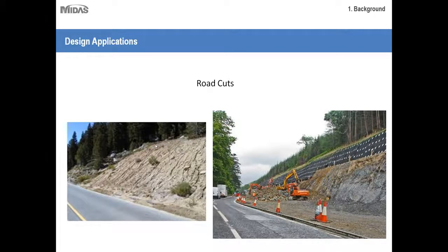As you can see, because the slope appears to be made of harder or stiffer materials, there aren't any tiebacks, and it's very close to the road. So in other words, the engineers found that this slope was stable enough or safe enough to not warrant any remedial measures, and it isn't made further away from the road.